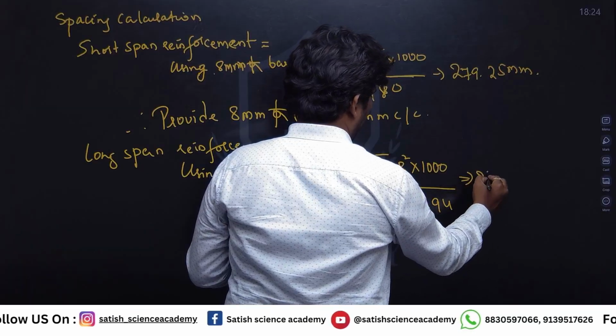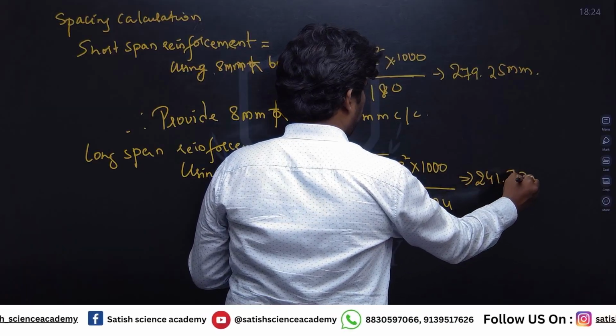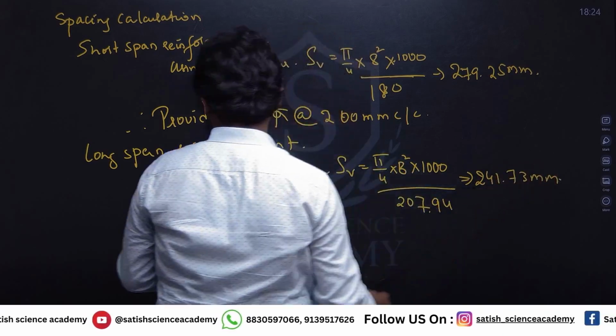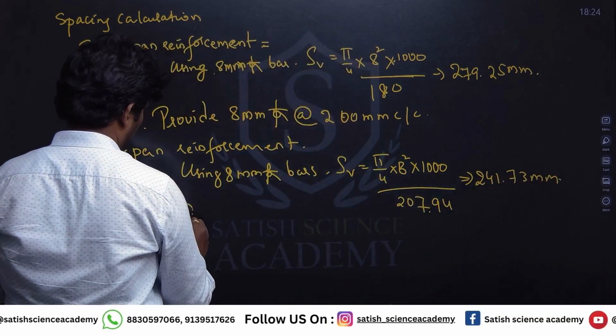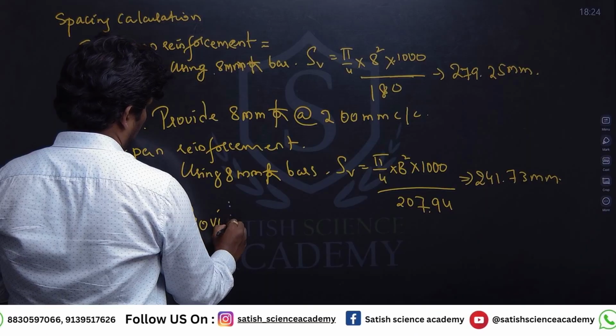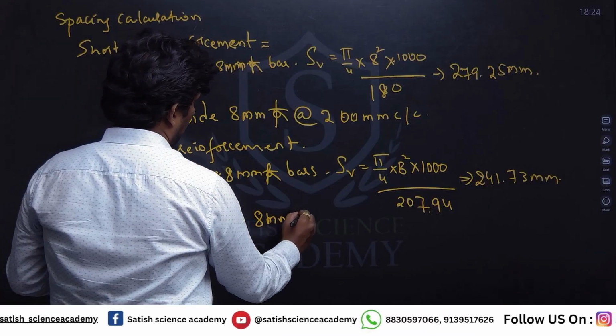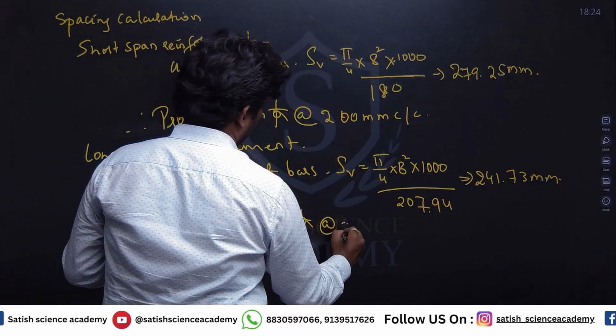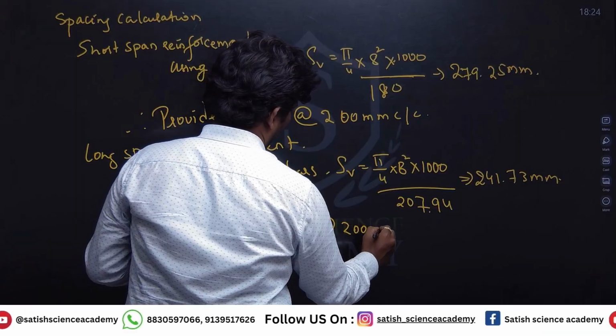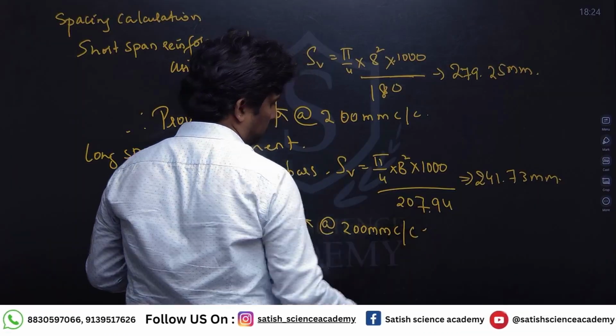This is 241.73 mm. Therefore, provide 8 mm dia at 200 mm center to center.